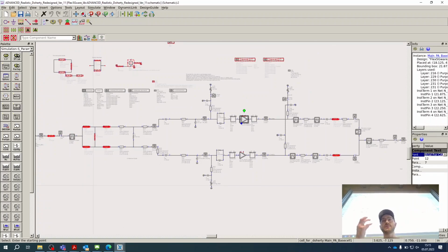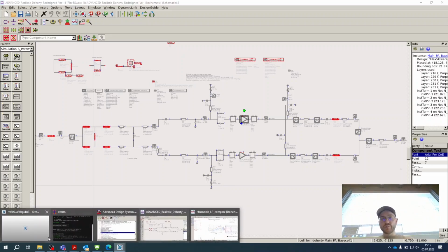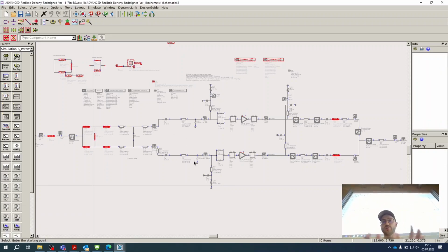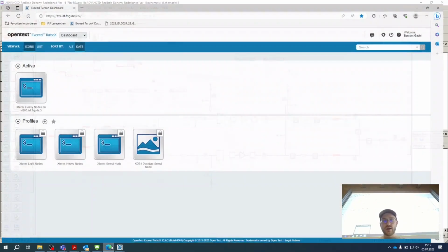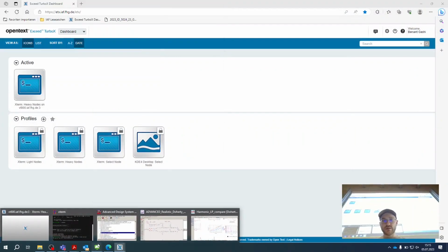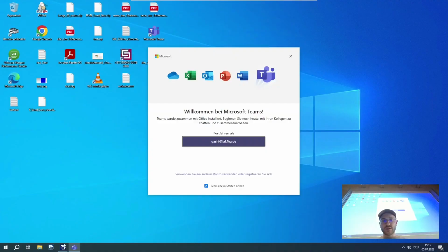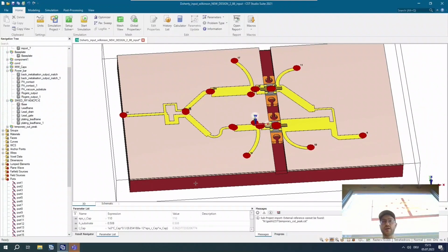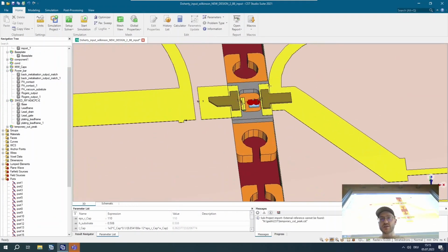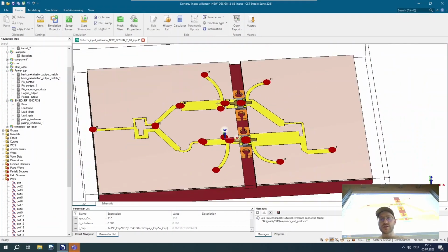And this is the most realistic way of simulating both temperature development and RF performance of the device, and how design is really done. This is how you work as a designer. You operate in ADS, you design it with schematic components, then you lay it out. The laid out file is then simulated in CST, as we see here. You take your layout, you simulate in CST, you have your packaging integrated in CST, you have your matching and so forth integrated in CST, and then you take this CST information back